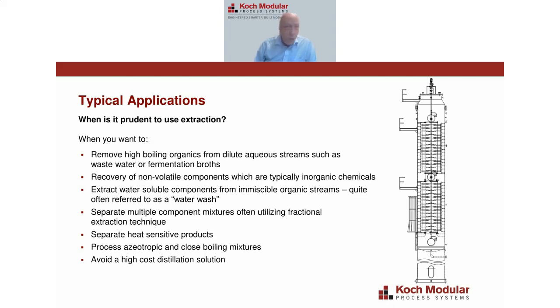Then the third one is when water is the solvent in an extraction process. Typically, if you have an organic stream with something in there that you want to remove, maybe salts, maybe residual catalyst, whatever, you use water to selectively extract those materials from your organic stream. So a lot of people have in their plant what they call a water wash. Sometimes it's a batch process, but again, what you're typically doing is a liquid extraction using water as the solvent. And then you can see there are a few other cases where you might use extraction for various reasons.